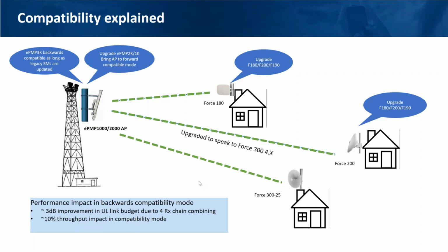What the MU-MIMO antenna does is, the two antenna elements, the overlapping 90-degree sectors, essentially allows us the most optimum way of trying to group subscribers within a 90-degree sector. And we're doing some phase shifting between the two subscribers that we talk to, and that's what we're using on those two 90-degree sectors. And I think this question probably goes back to questions about using other antennas and being able to do MU-MIMO. That's something we're looking at in terms of a roadmap, but not coming out with on day one.